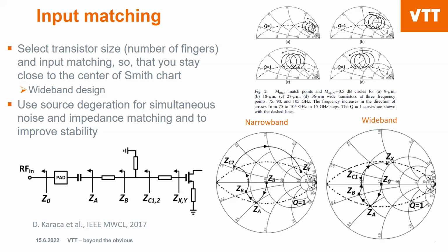As I said, the series transmission line moves around the center of the Smith chart the longer you make it. So you can see that we move on point ZB. Then we have the short-circuit shunt stub, which moves on. You can plot this Smith chart on the impedance plane, but you can also plot it, as in the previous figure, on the admittance plane. So it's like a reversed Smith chart.